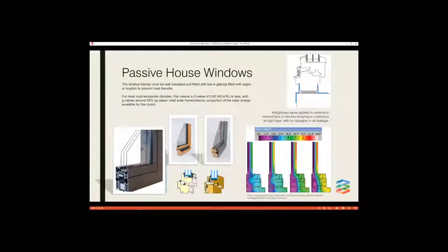So what does Passive House actually require? Passive House requires thermally broken windows, so we're not having an energy transfer through the frame. What we don't want is heat flowing through our frame. So we have a thermal break, and you can see the different types of construction in these frames. We've got the three primary types of frames that you can have: aluminium, timber, and then a composite. You can get UPVC as well. They're quite common in the industry, and they all come thermally broken.